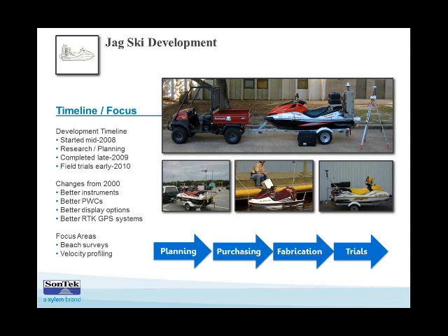But also, as you'll see in a following slide, the velocities going through there would reach over 2 meters per second. So it was a bit of a challenging place to do the survey. We stayed out there for about 9 hours, collected water quality samples with the Seakeeper system, all the while doing the ADCP profiling. So we ended up with over 100,000 measurements of velocity over the 9-hour period, all collected through actually the River Surveyor Live software package.